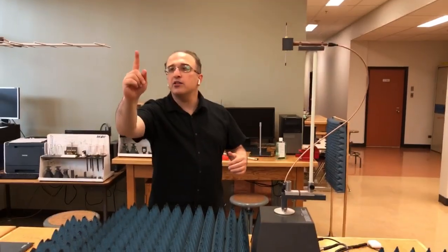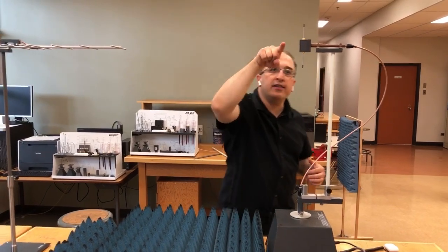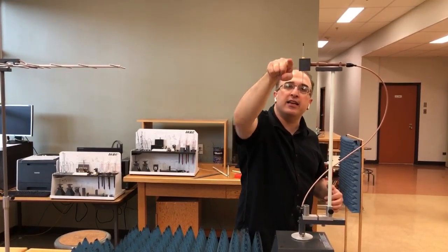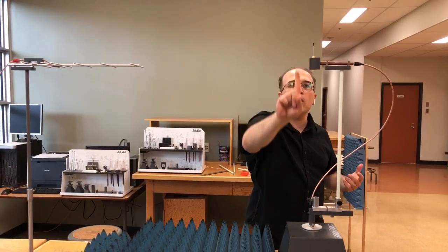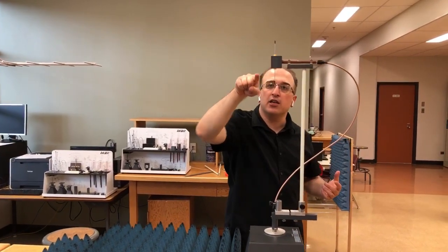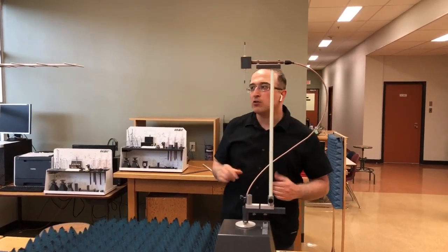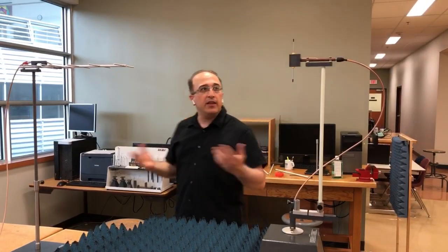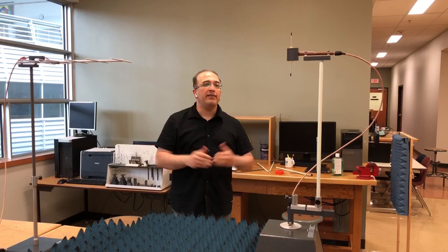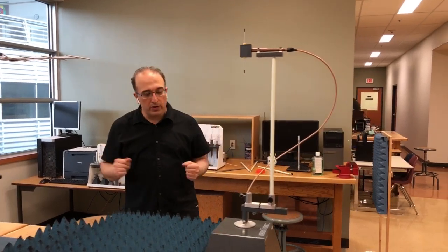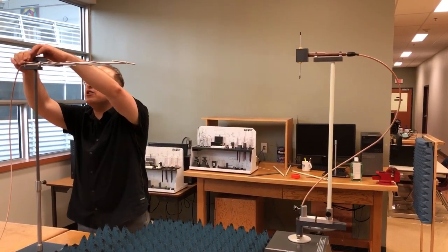So this is now horizontally polarized. So the electric field is moving in this direction. So ideally, this should not create any received signal on the dipole, because the movement of the electrons on the dipole is supposed to be in this direction, but the electric field, which is essentially our force, is in this direction. So ideally, there would be nothing, but then as you see in practice, we're gonna get some cross-pol component, and the level of cross-pol to co-pol is our cross-pol level. So this is now ready for starting the measurements.